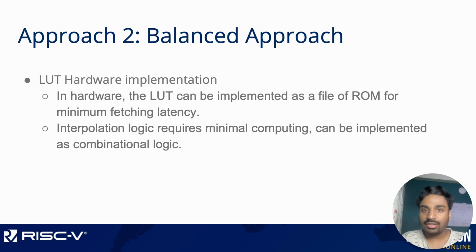Finally, coming to the hardware implementation of the LUT, we can implement the LUT as a ROM for minimal latency. Usually this can be done in 2 cycles. In my code, I've assumed a latency of 2 cycles for fetching data from the LUT, and the interpolation logic is minimal and can be implemented as combinational logic. No DSP is required. So all in all, this becomes a very efficient implementation.